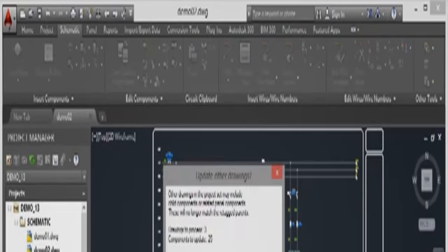So I click on OK, and you can see that processing down there on the command line. So it's reading the project database file. Now it's telling me there are some other drawings that are linked to this particular drawing that include child components or related panel components as well. These will no longer match the re-tagged parents. I've got drawings to process 3, components to update 25, breakdown by category. There's a panel symbol update. So there's 25 over on the panel symbol that need doing.